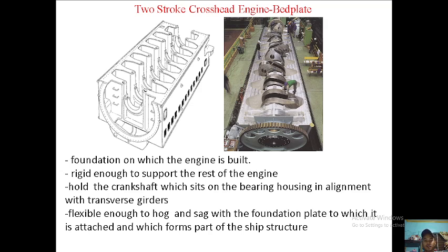It is rigid enough to support the rest of the engine, and it holds the crankshaft, the bearing housing, and it should be flexible enough to hug and sag with the foundation plate to which it is attached and which forms part of the ship structure.